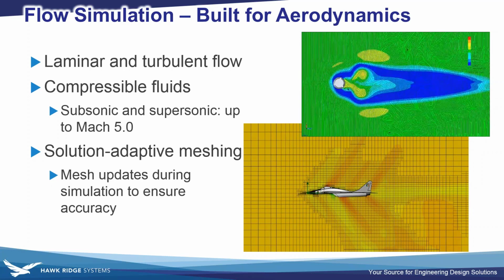And so in most of these situations, particularly if you are interested in the large scale aerodynamic performance of the whole craft, Flow Simulation is more than capable of using the Navier-Stokes equations to calculate all those parameters. And the turbulence model is automatically encoded so that you don't have to manually set it up or specify the parameters you want. Flow Simulation can also handle compressible fluids, like any gas is, and that becomes particularly important when you get close to high subsonic or supersonic speeds.